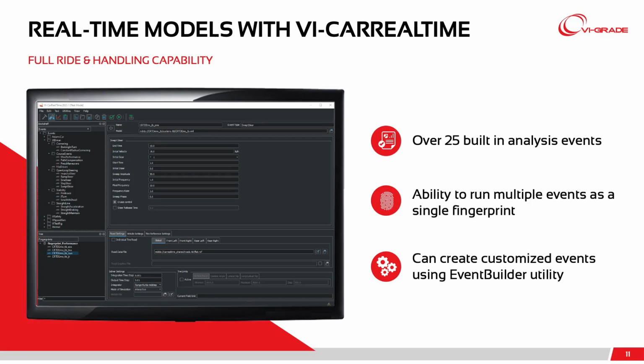We have, well, first, over 25 built-in analysis events with a GUI that's standard, that you can select from a tree, and then each one of those analyses has a certain set of standard parameters that are defined by it that you can create. You can also take multiple sets of analysis and string them together into what we call a fingerprint, which you can treat as just a one submittal job that will run multiple analyses and generate all the results for you. And then finally, all of these events get defined out of the GUI through a file format that can be accessed by a utility called Event Builder, that you can modify those events, you can create your own, you can string multiple ones together. So it's very robust for setting up an analysis.